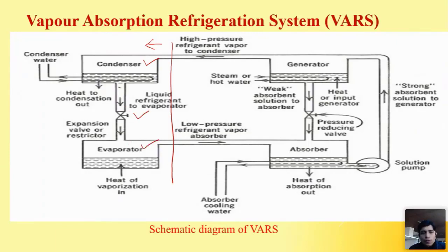What we are changing is, we are replacing the whole bulky right side system to reduce the energy consumption which was demanded by the compressor. So this is our requirement, and how it actually works we will discuss. Okay, so say I'm taking an example to explain this figure. Assume that our refrigerant here is ammonia. We all know that ammonia has very good solubility in water. Okay, and whenever ammonia mixes with water, an exothermic reaction takes place.